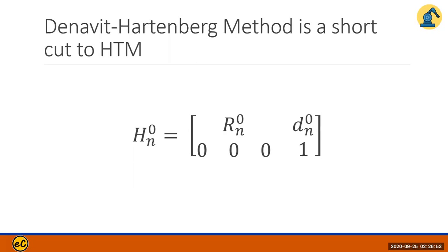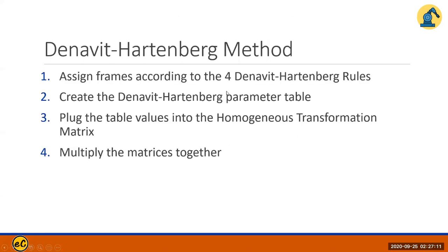A homogeneous transformation matrix can be written like this. You have a rotation matrix, a displacement vector, and a 1. And we write it down like this. We talked about this homogeneous transformation matrix in the previous lab. So now we are going to have a systematic way of developing the Denavit Hartenberg method and matrices. First, we need to have rules. There are 4 steps.